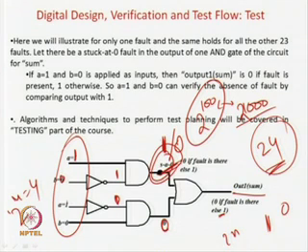So that is what is called structural testing. What do we do in structural testing? We forget about the functionality of the circuit. We take a fault model; stuck at 0, stuck at 1 is a very well accepted fault model. Then we find patterns like this. If there are n lines in the circuit, 2n patterns will be found at max, which can assure you that none of the lines in the circuit has a stuck at 0 or stuck at 1 fault.